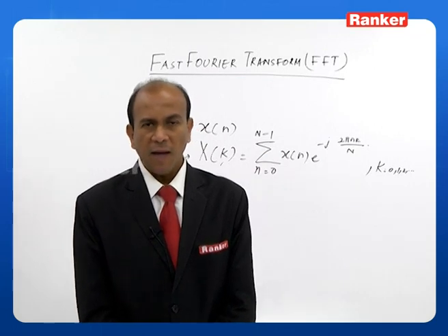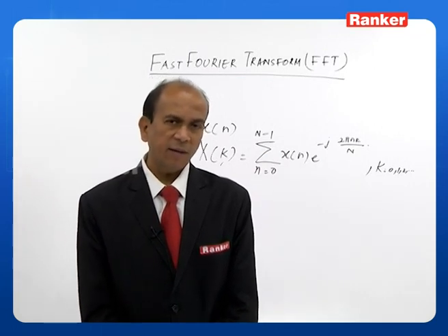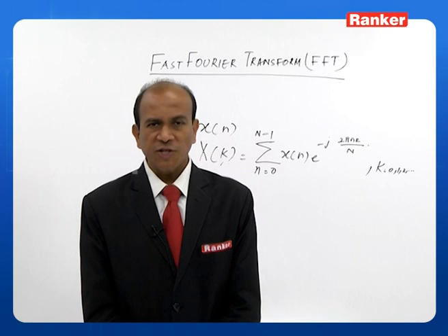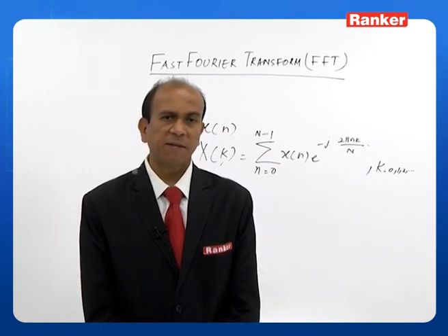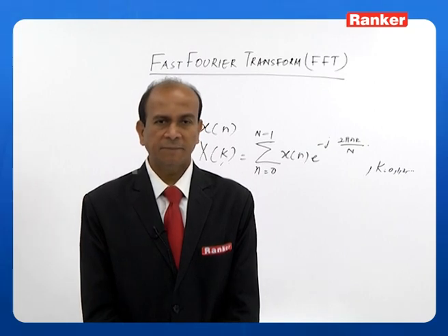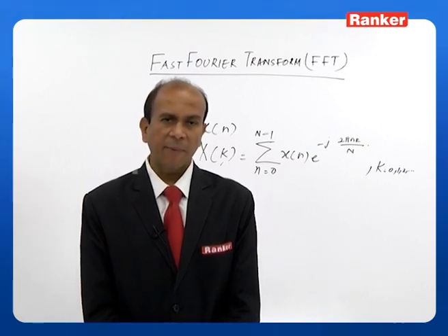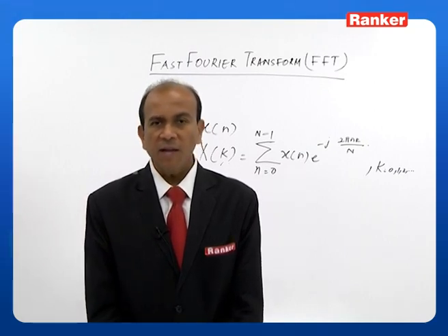As you see here, the direct representation, earlier N squared, is now changed to the logarithmic scale. So that is given by the number of computations being log N to the base r, where r happens to be the radix of the FFT.